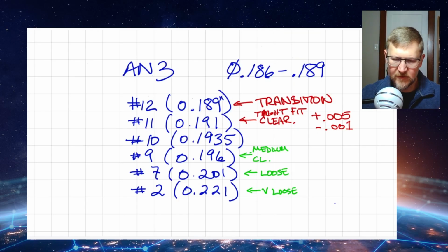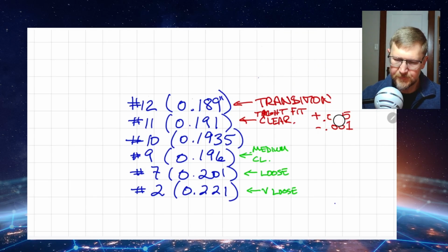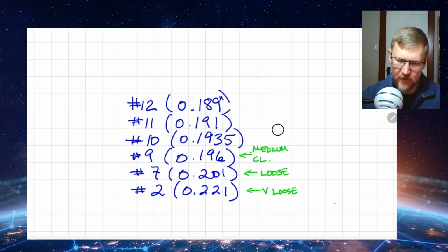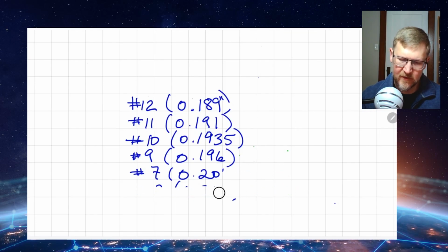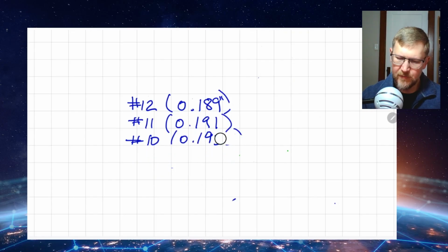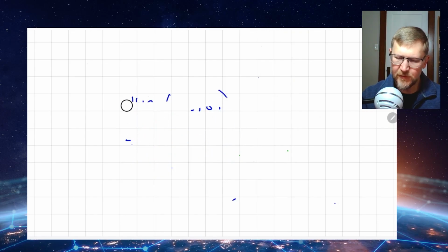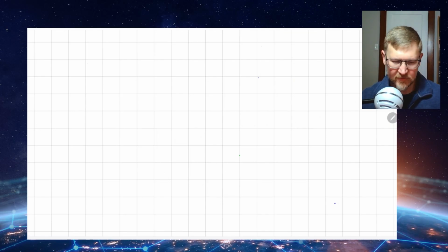So let's talk for a minute about tolerancing of everything in terms of the locations. So let me clean this up. We briefly talked about drill bit tolerances. And again, you can tighten some of those up if you use different manufacturing techniques. But you want to keep this as simple as possible, right? Because the more complicated and the more precise you get, the more expensive things get, and the more advanced techniques you need.